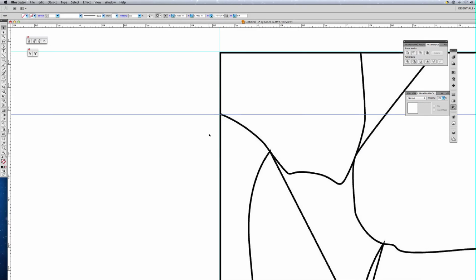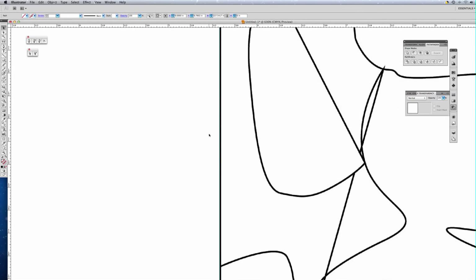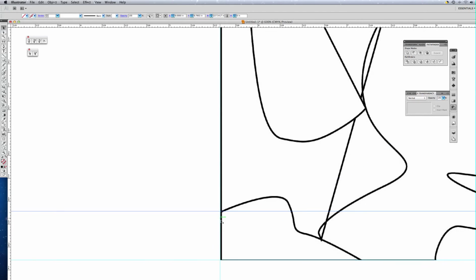Okay? We're going to scroll down. We're going to look for any other ones on the left side. So we're going to get our ruler again. Click and hold at the top of your ruler. Bring it down to where this line intersects and touches your boundary from tile to tile. Get about center and release.